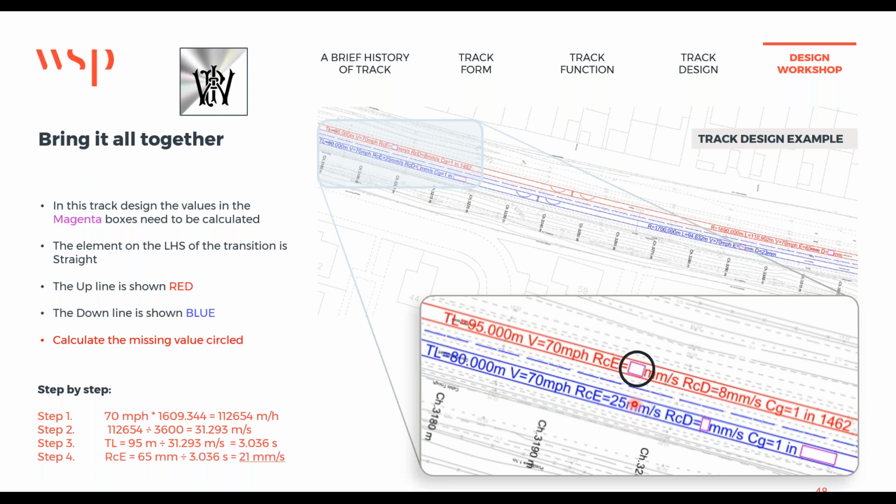So what have you got? You've got your rate of change as your 65 millimeters divided by 3.036 seconds, or 21 millimeters per second. And that one over there gives you a little bit of a clue. That one was slightly higher because the transition length was shorter. See, that was a 95 meter transition. This was an 80.